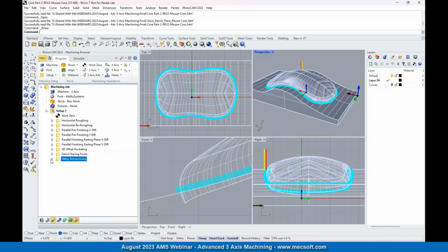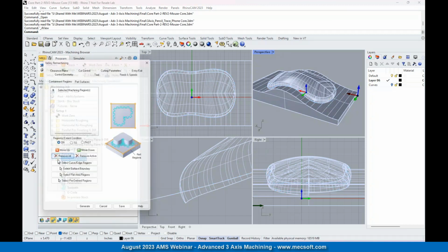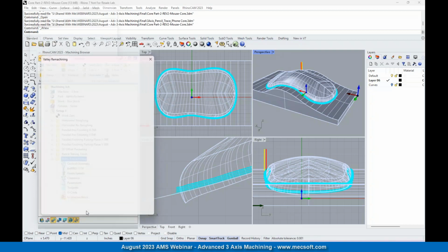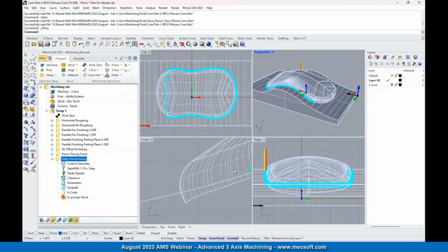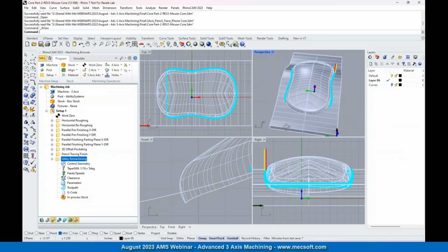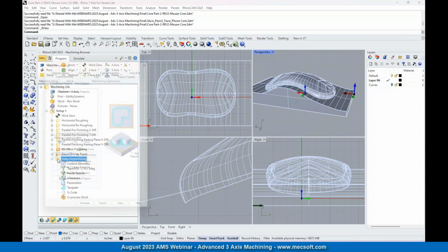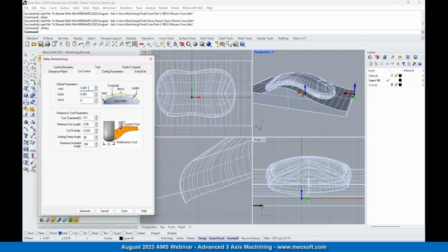And if you do that with a taper mill, I think, as I mentioned, the performance of straight ball mills is much faster than the taper mills. So if you want to, we can go ahead and change the tool if you want to see the difference. Taper mill 1/16 5-degree. It looks like it didn't go all the way around though, did it? Not sure why. Let's go in here and see if we need to tighten that. Maybe that's why I had it tighter.